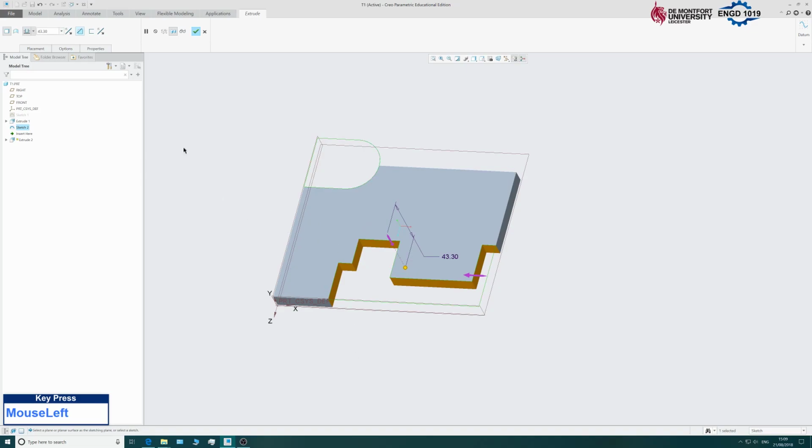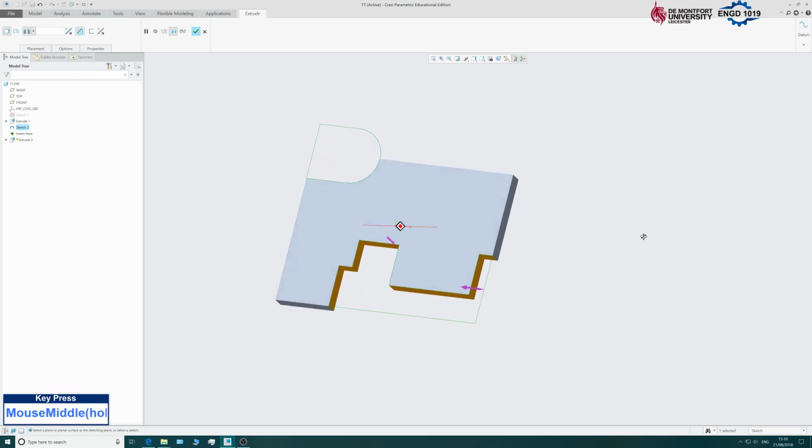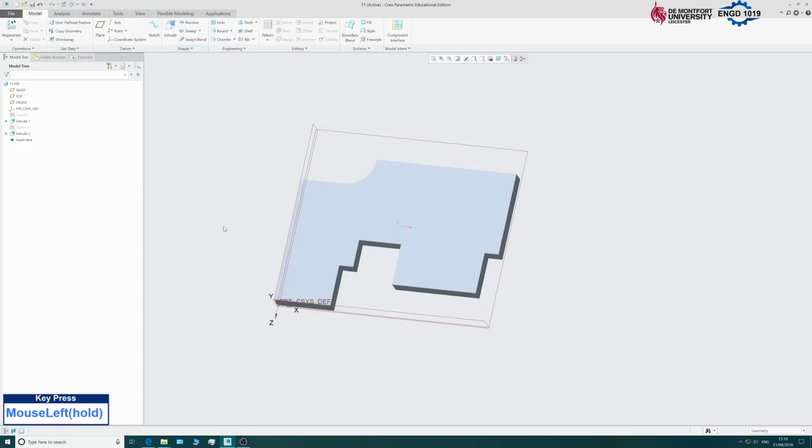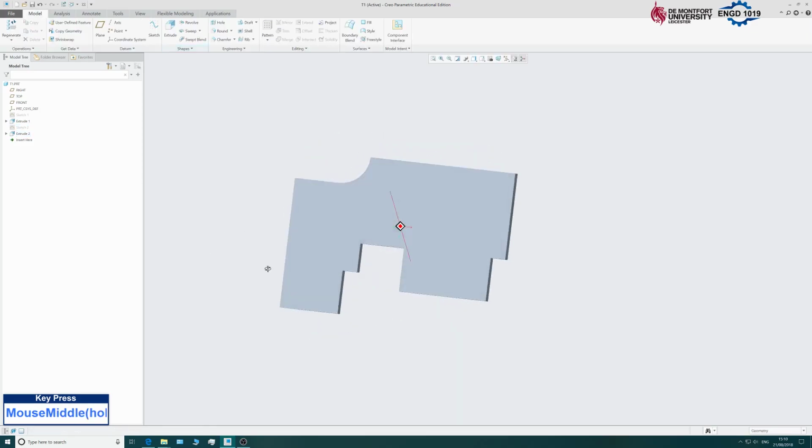And obviously we can set the thickness for the cut, but there's actually a really handy tool in here. If you go to this little drop down menu, you have this one, and that basically means that it will go through all of the material that's there. Okay, once we're happy, we just click the little tick mark. So we've got the basic outline for the shape.